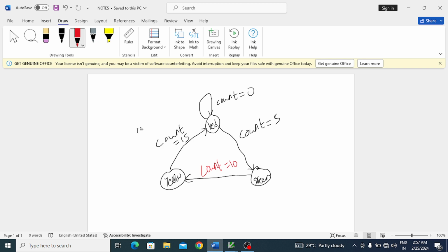If each clock edge takes 1 second, we have to count 5 clock edges to stay in that red state for 5 seconds. So we count the clock pulses to measure the time. This is the actual functionality.